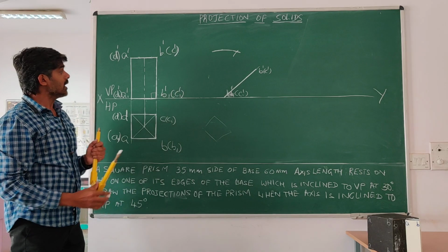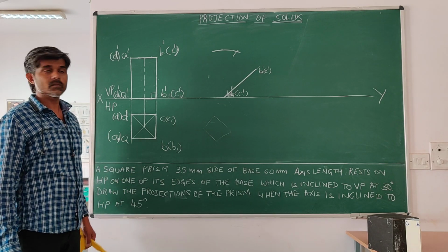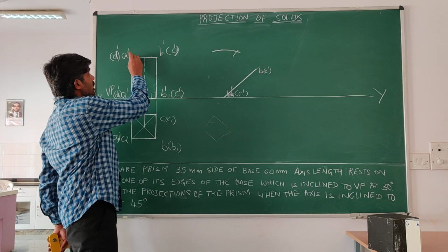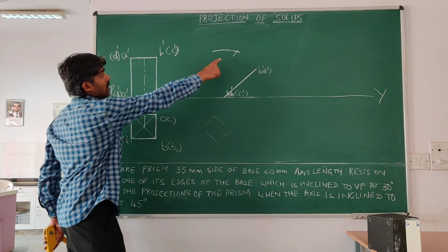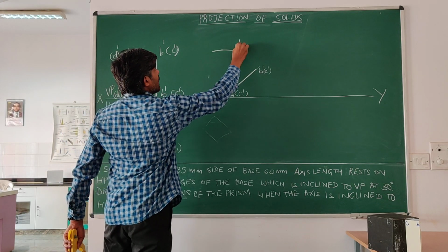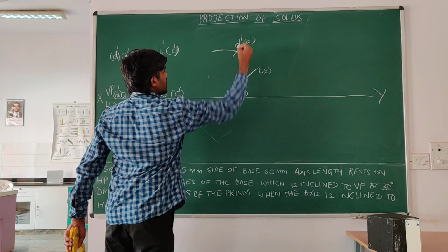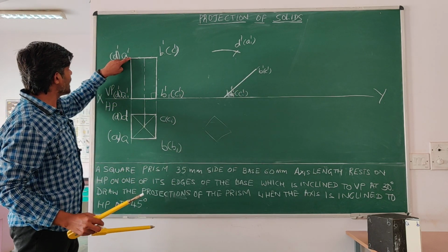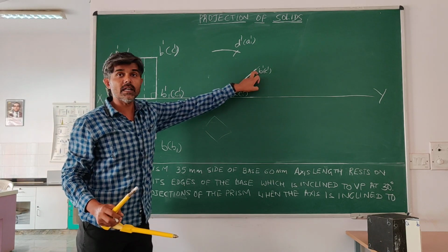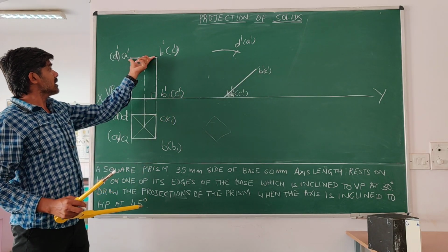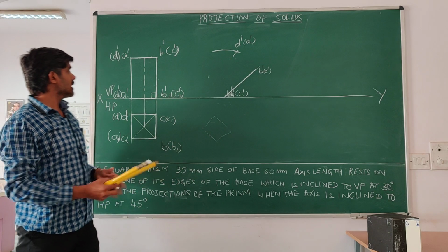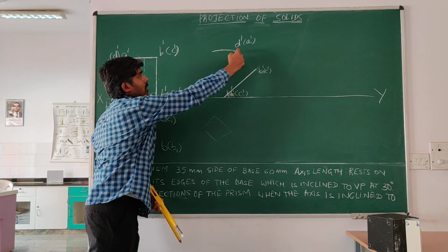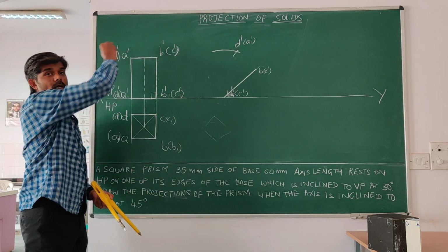Now what I tried was to get the location of this point, that is B1 dash in bracket A1 dash. Sorry, this is B1 dash. So I had these two points already located. I took the length from this side and drew an arc, and then I took the length from this point and drew another arc. So the intersection gives me this point.